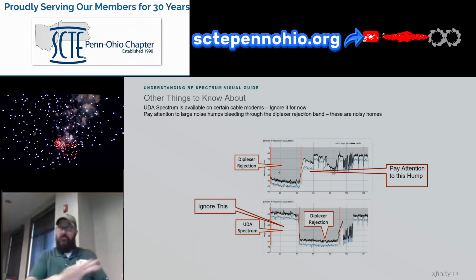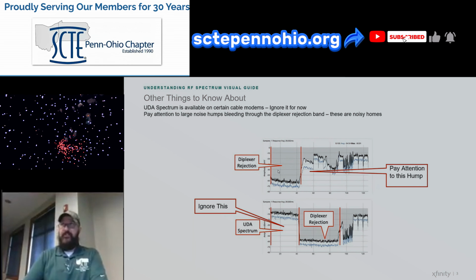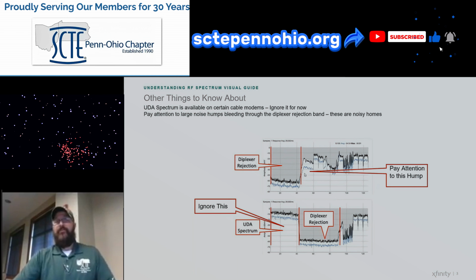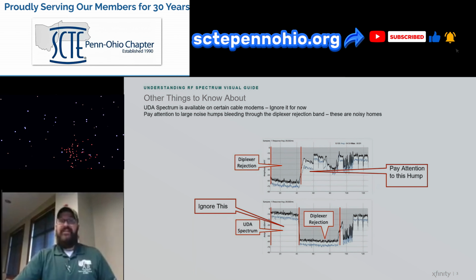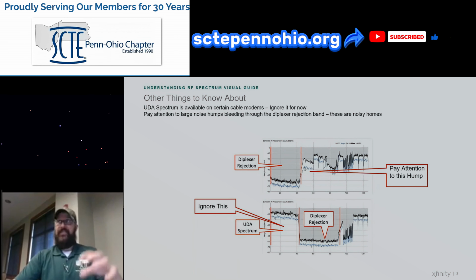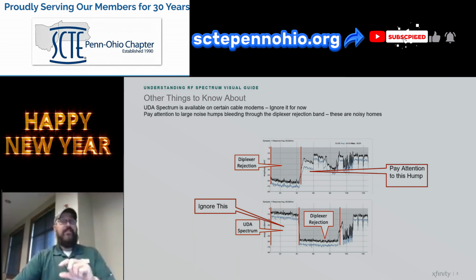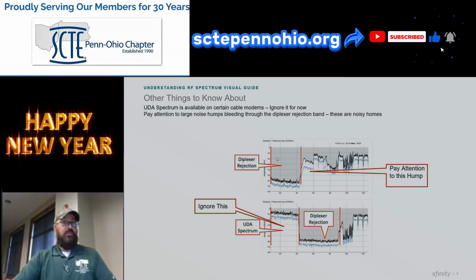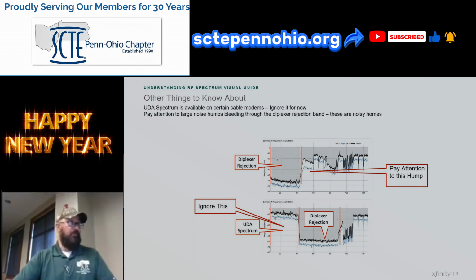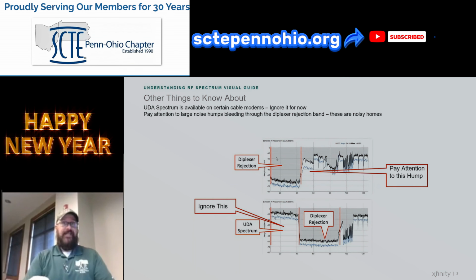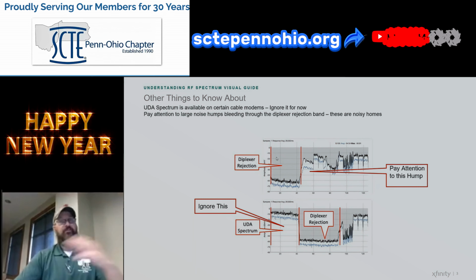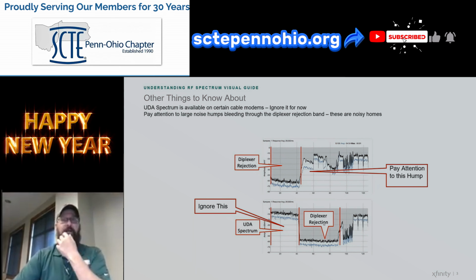That portion of the device is actually used to transmit information upstream, so it doesn't represent any of this energy in the downstream. But you can extrapolate that this elevation inside the premise on the downstream at this device likely includes the sub-split portion of the spectrum too. So the energy is there, the diplex is just cutting it off so you can't see it in the downstream.